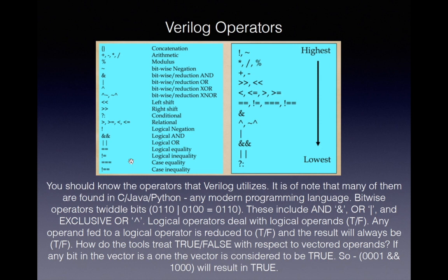Type some equations, run the simulator, see what the results are. Just to convince yourself what is the difference between logical operators, bitwise operators, what an exclusive OR is, what the reduction operators are. We'll use the reduction operator immediately on the design of our UART.